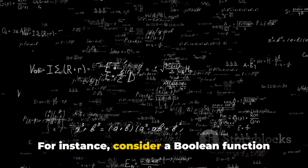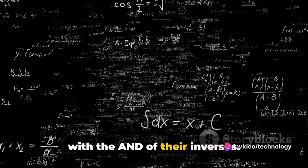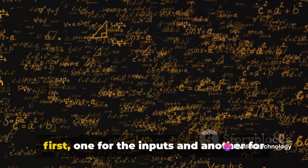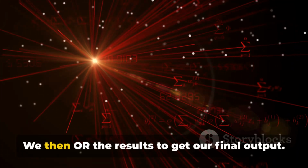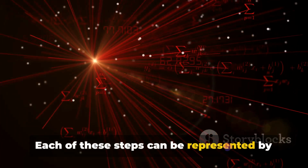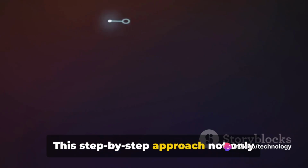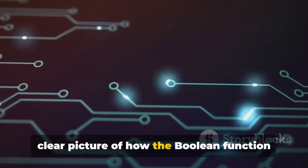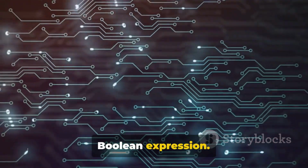For instance, consider a Boolean function where we're ORing the AND of 2 inputs with the AND of their inverses. We start by evaluating the AND operations first, one for the inputs and another for their inverses. We then OR the results to get our final output. Each of these steps can be represented by a separate column in our truth table. This step-by-step approach not only simplifies the process, but also provides a clear picture of how the Boolean function is working. It's like having a roadmap for your Boolean expression.